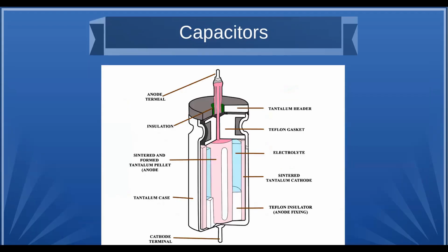This is a kind of a cross section of a tantalum electrolytic capacitor. So you've got, I'm not sure how well you see, but this outer, what they call sintered tantalum, and an inner. Sintered means it's made up of ground tantalum that's sort of pressed together. So there's holes in it. It's porous. And then there's an electrolyte in there, and it is what actually carries the charge between the two. But that's typical to an electrolytic capacitor, not necessarily all tantalum. That's more modern.